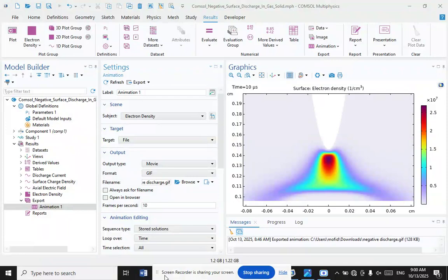Dust accumulation decreases the photovoltaic (PV) performance and also hampers the lifespan of the module. It hinders the sunlight from penetrating through the PV module glass and obstructs it from reaching the solar cells. Consequently, the resultant effect creates a drastic drop in PV performance.